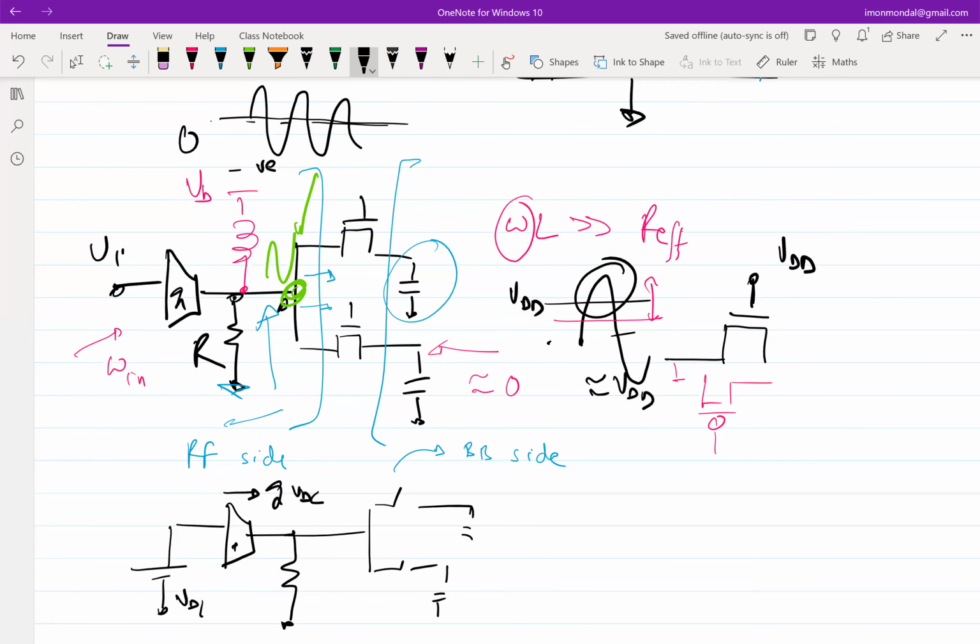So what implication does this have here? There are two implications. One is, if you want to pass a signal, these guys will be driven by some set of inverters, right? In your assignment, you assume these are ideal waveforms, but in a real receiver, you have one sinusoidal waveform somewhere, you have to convert it into a square wave and then drive it using a set of buffers.